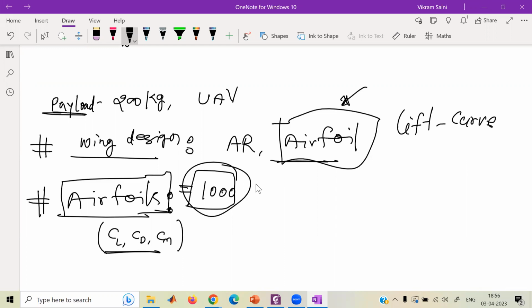Have any one of you taken any flight dynamics course? Any flight dynamics course? No, sir. So you will require mass and inertia properties. You will need an inertia matrix for the aircraft, inertia about all its body axes, right? Yes, sir. Because the structural group will determine the mass distribution, and based on that they'll give me the total mass of the aircraft and the inertial properties.